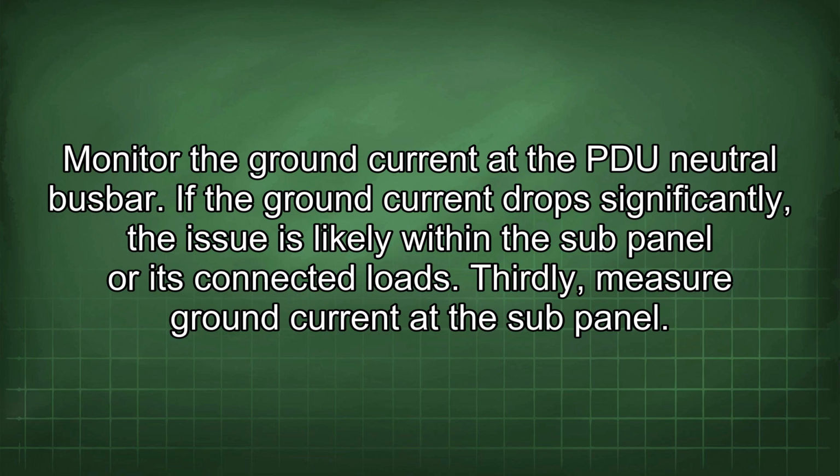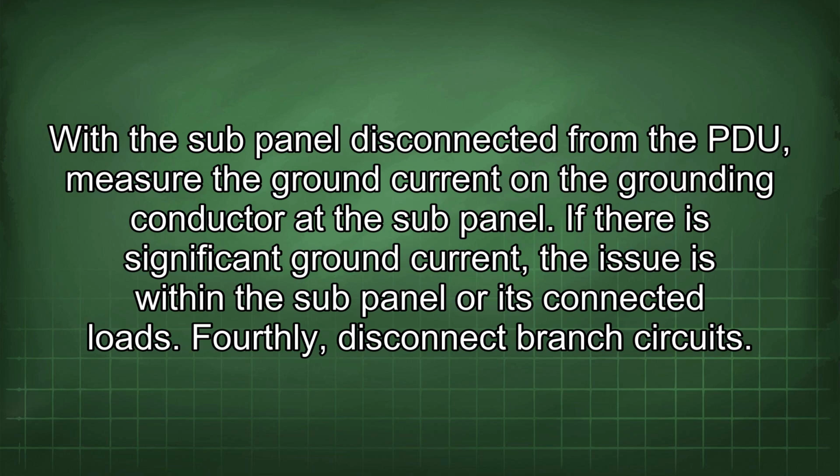Thirdly, measure ground current at the subpanel. With the subpanel disconnected from the PDU, measure the ground current on the grounding conductor at the subpanel. If there is significant ground current, the issue is within the subpanel or its connected loads.